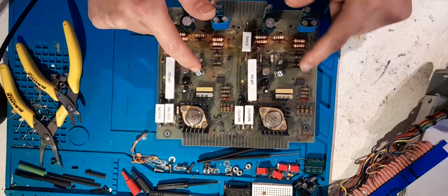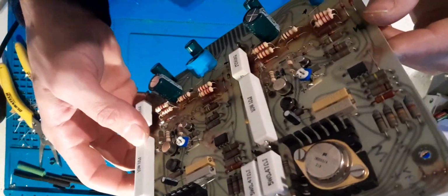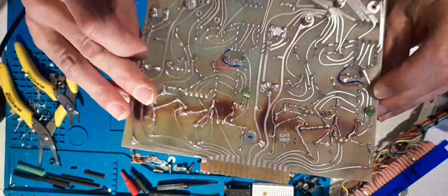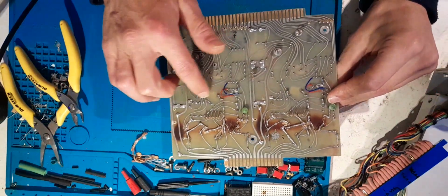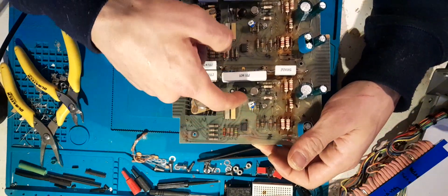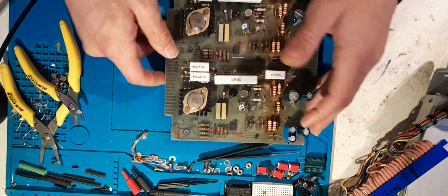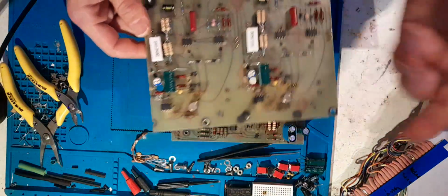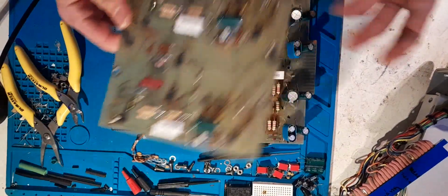Okay, so I've made those references up, mounted them as flush to the board as they go. Actually looks quite neat if you ask me. They're soldered in. So there's space to tack capacitors across here on the back and across there in this little space here on the front. So both of these onboard references have got plenty of space to add capacitors.